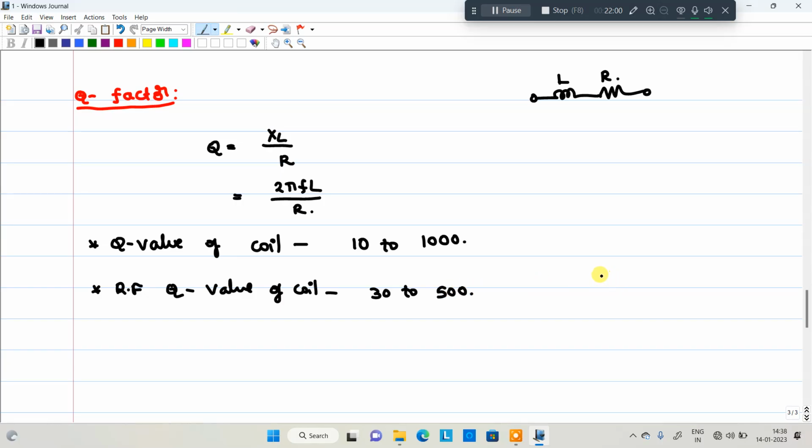So you know at low frequencies R is just equal to the DC resistance. In this particular case, low frequencies, the AC value is the same as the DC value, both are the same. But in case of higher frequency, the effective values of AC and DC resistance are different. The reasons behind it, we have three effects. Why is it different, the AC resistance and DC resistance? First one is skin effect.